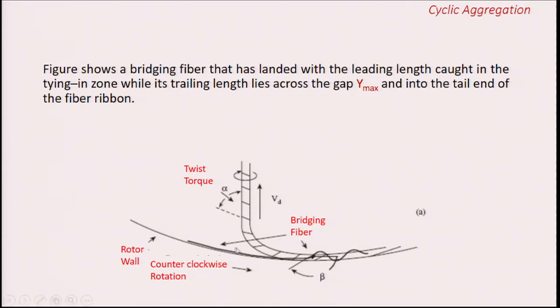As the fibers are getting deposited onto the gap also, these fibers come in contact with the already formed yarn. Okay. So, obviously, these new fibers cannot go into the core of the yarn. They can only take the surface and just wrap around it, and this wrapping is going to depend on where exactly the fiber is going to be meeting the yarn arm.